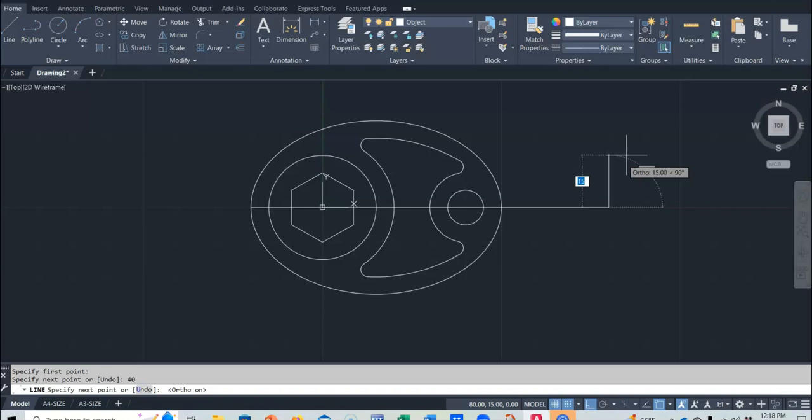If I take a look, it gives me the dimension of 15, and then the tail itself is 10 wide. So again, I'm dragging it in the direction I want and putting in the dimension, and then I can go down, in this case another 10, and go straight over. It really doesn't matter because I'm going to trim it off. Make sure you don't object snap it. See this object snap? That's overriding it. You can always turn your object snap off and then just drag it.